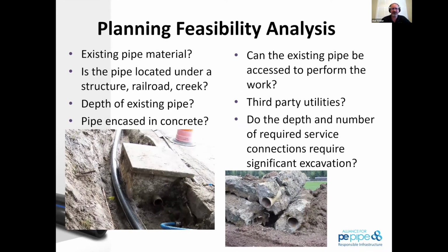Really, in a feasibility analysis, what we want to collect for data, like you would do on any trenchless project, is to look at what the pipe material is, and whether or not we're going to be able to access that pipe if we have a problem. Just because a portion of the existing pipe being burst is encased in concrete does not mean that your project is over and dead in the water.